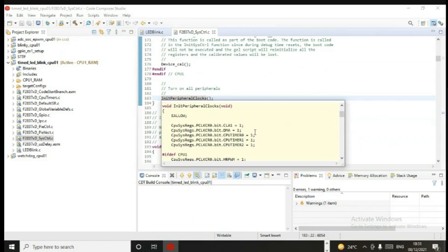So if a counter is in your inbuilt module, it has to be serviced by the CPU clock, with certain clock dividers. Timers run independently of the main CPU clock; they are not dependent on the main controller clock.